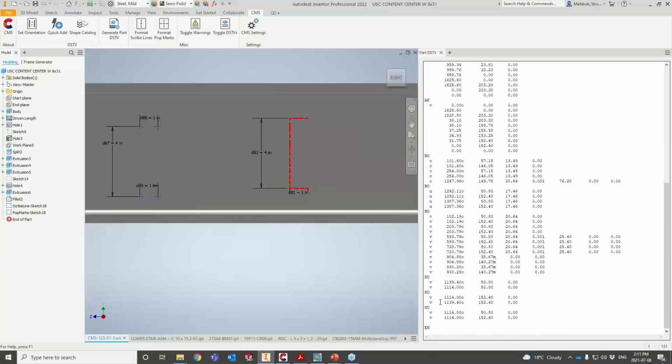your DSTV window. So as you see, those are the KO blocks. The KO stands for your marking lines. So as you see, I have 3 blocks because I have 3 lines here, right? Additionally, I had 4 pop marks, as you see. Those are the pop marks, shown as a small m on the lines, and I have no diameter associated to those drills. So that's why it's a pop mark.